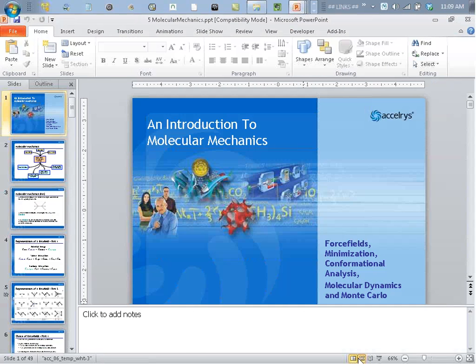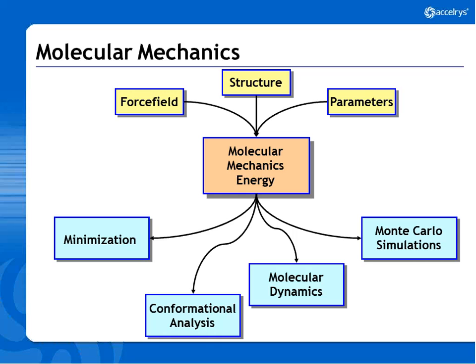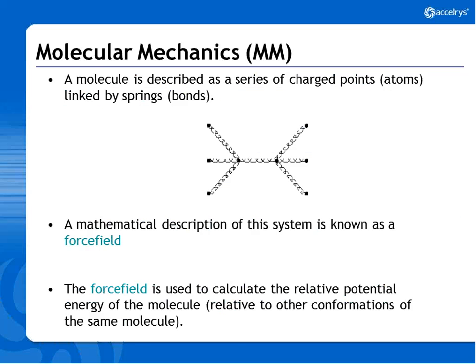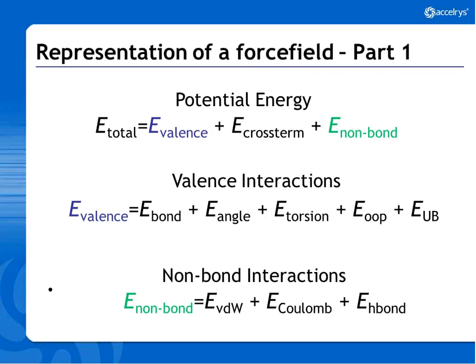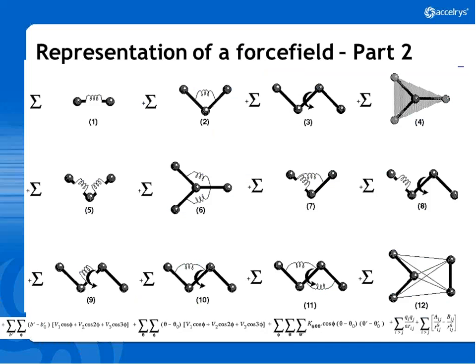One of the core parts of Material Studio is its ability to handle force fields and force field systems, right? In essence, you can do conformation analysis, molecular dynamics, minimization, Monte Carlo simulation, step analysis. You require a force field parameter set, you require a structure, you require parameters, right? Molecular mechanics, everyone knows, is a set of springs. There's a whole complex series of parameters that go into a force field, whether they be just linear extensions, angular extensions, torsional extensions, out-of-plane bending extensions, what we call improper terms that keep ammonia pyramidal, etc.